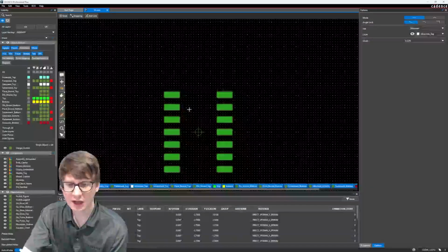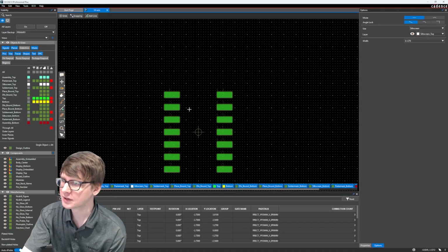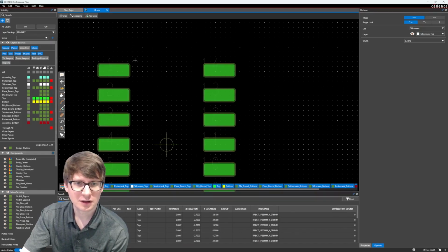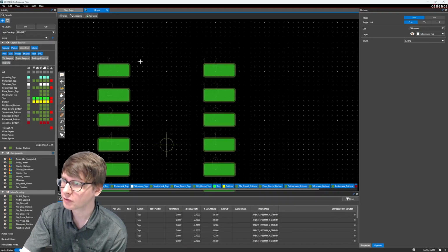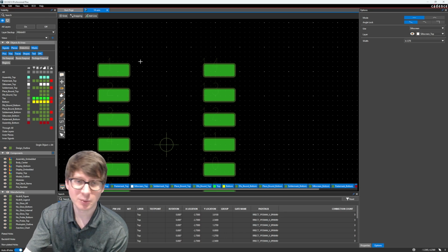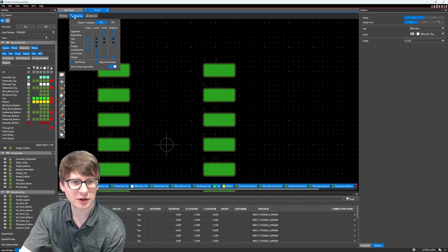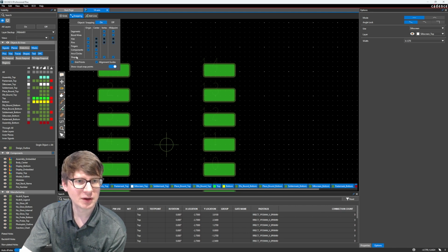And again, because our component is 8.6 millimeters tall, we're going to go ahead and measure out 8.6, so 4.3 millimeters, and that's where we're going to draw our line. Now, if we look at the bottom right here, we get a nice little indicator of what the grid point is that we're starting to draw at. And if we look at our snapping, you'll see that I believe we are snapping to grid points here.